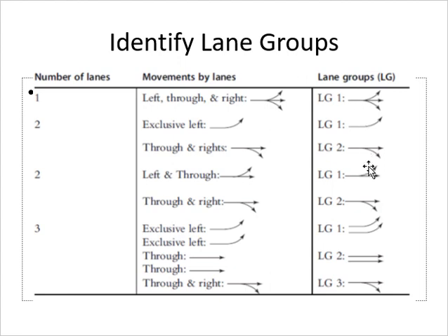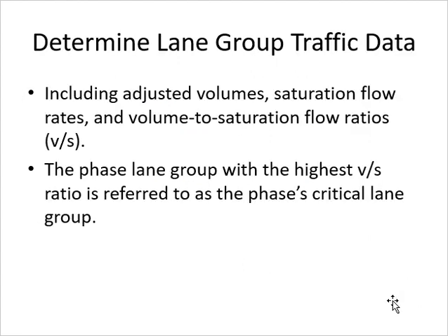Okay, so whenever any movement is changing, we put it in the other group. So these two lanes have the same movement, and these two lanes have the same movement. This one has a right turn added, so it's in the third lane group, you can see it here.